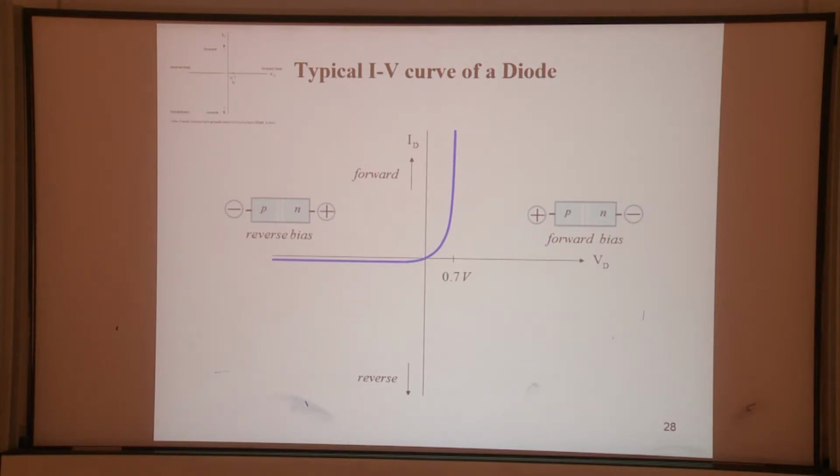But Doctor, experimentally, when we just increase the voltage above 0.7, it has no effect on the current. You cannot adjust to 0.7. Before you adjust to 0.7, there's a lot of current. Then you'll burn your circuit. Well, usually there is resistance, right? So it will counterbalance each other. So you will not be able to even reach 0.7. Because at that time, when the diode voltage is near 0.7, you cannot feel that the PN junction exists. The circuit is conducting. It's now like an ohmic contact, hardly any resistance. So you will not feel the presence of the PN junction. All right?